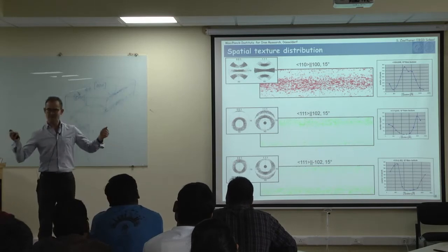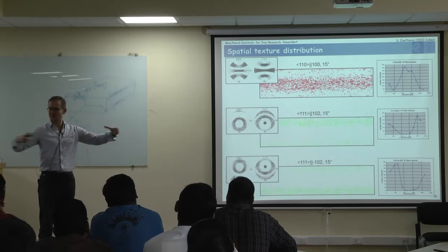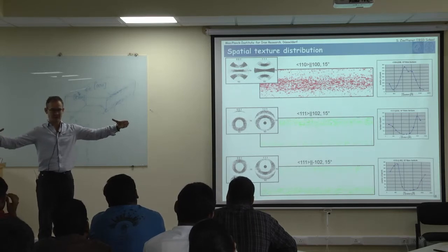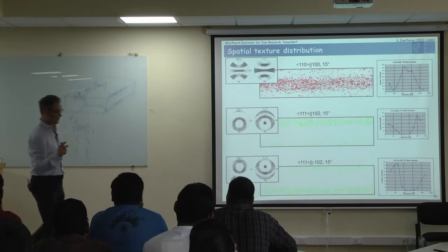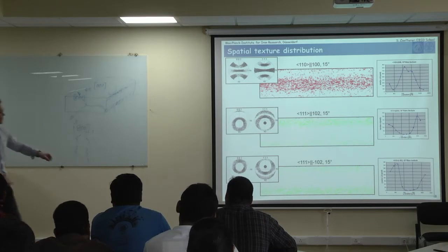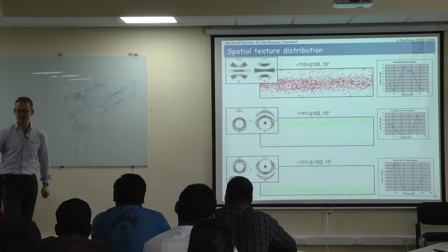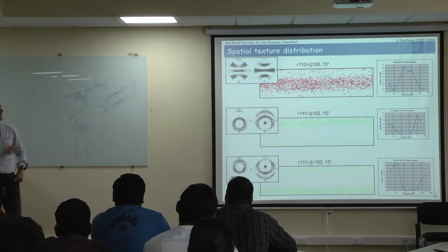And you remember my example with the Gauss texture. This Gauss texture leads to this enormous Gauss grain growth. And these Gauss grains in these rolled materials grow only very close to the surface. They don't grow out of the center of the material, they grow from the surface. And this is actually iron silicon. This is the same material.